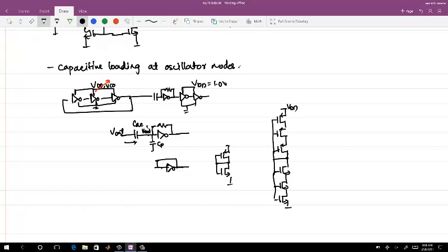Pardon? Rise fall for? No, so the thing is, if I am using this as a diode connected, the gain is effectively, yeah, but what is the drawback? Yeah, so this one actually comes with a CP2. This actually comes with a larger input cap. Your CP2 is greater than CP1. So the loading on the oscillator will be more, but the power consumption is lesser. So you need to do the trade-off, which means to a certain extent you can use this.